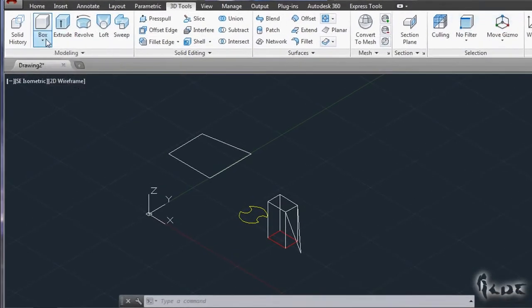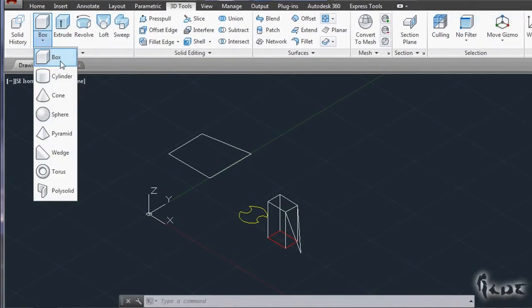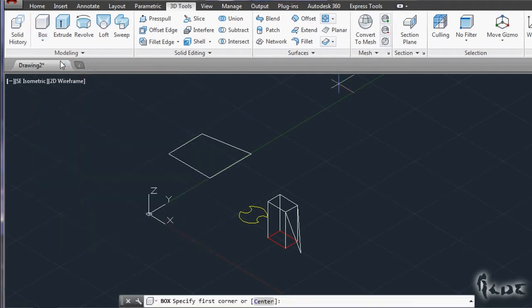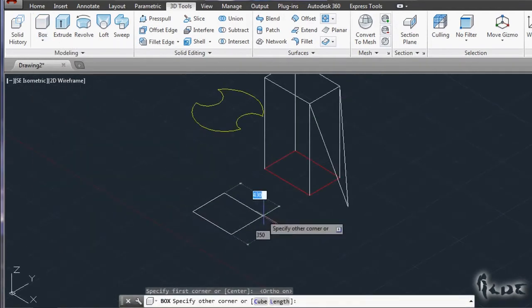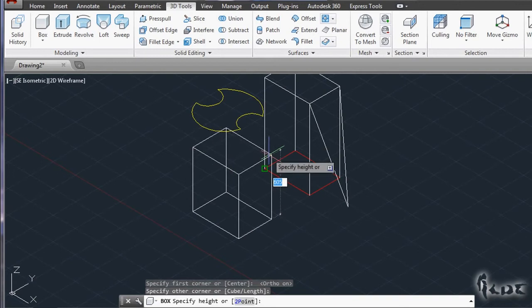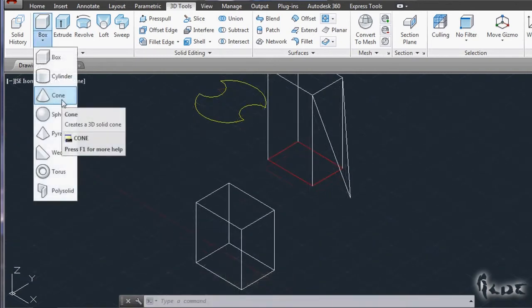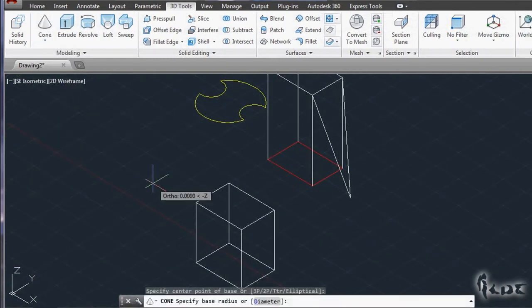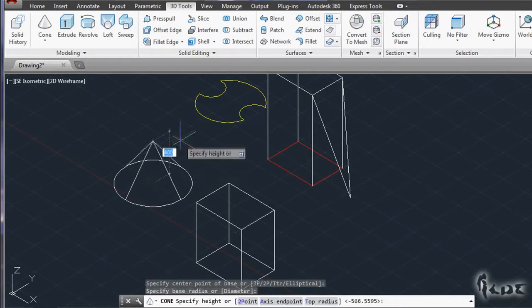3D Tools is like the Home window but dedicated to 3D designs. The section Modeling is used to create 3D objects. Some of them have curved surfaces, some others not. Keep in mind that the base, if the 3D object has any, is always drawn on the XY 2D space. Heights are rendered through the third dimension, following the Z-axis.